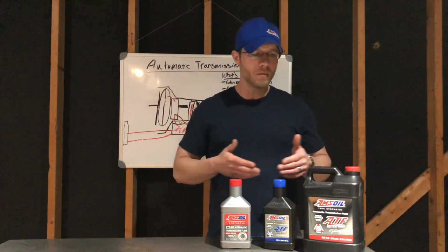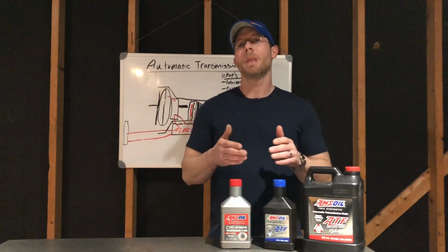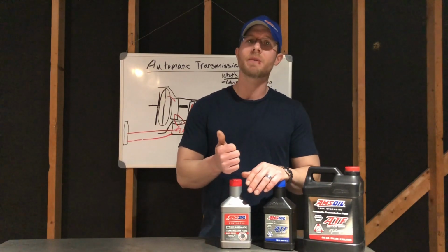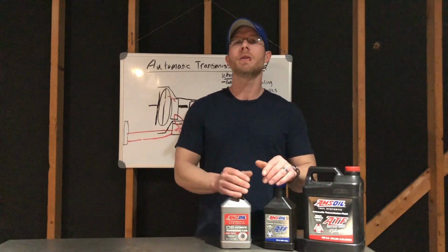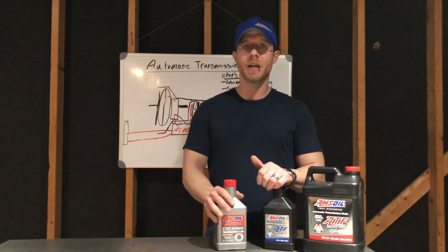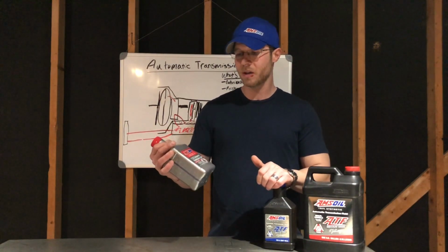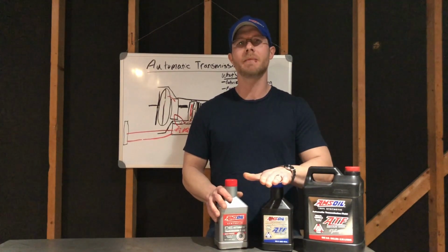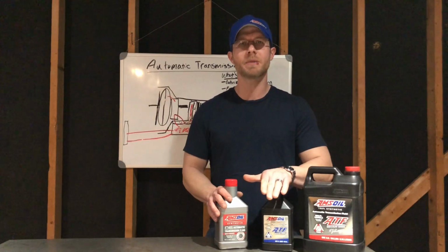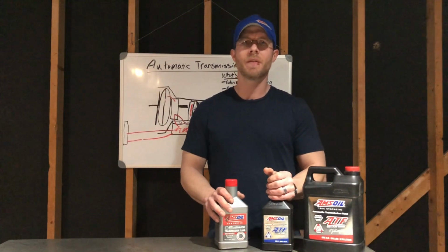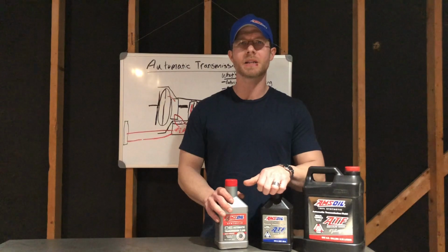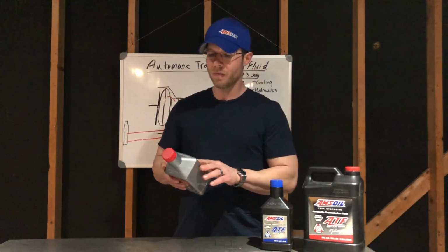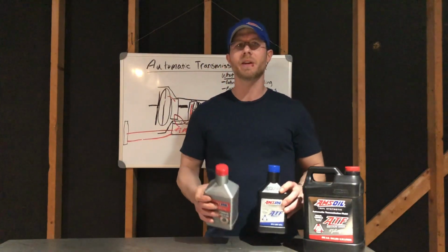So we've got a couple different products. There are more. They have transmission fluid for CVT transmissions and whatever, but this is your most common stuff. You've got OE in the multi-vehicle, and then there's also OE in the fuel efficient. The fuel efficient is the replacement for like Dexron 6, the GM transmission with the lower viscosity. So that's a replacement for that. Between these two, it covers almost every vehicle.